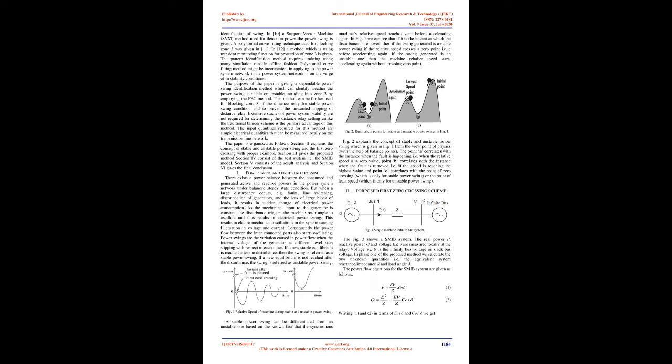The method of determining the swing center voltage is not dependent on the source impedance of the network and impedance of the line. Its magnitude is equivalent to the variation in source angle, and it is strictly between 0 to 1 per unit [8]. This scheme is only relevant for a system having only two sources. There is not a single literature available considering the SVC method applied for large power system network.